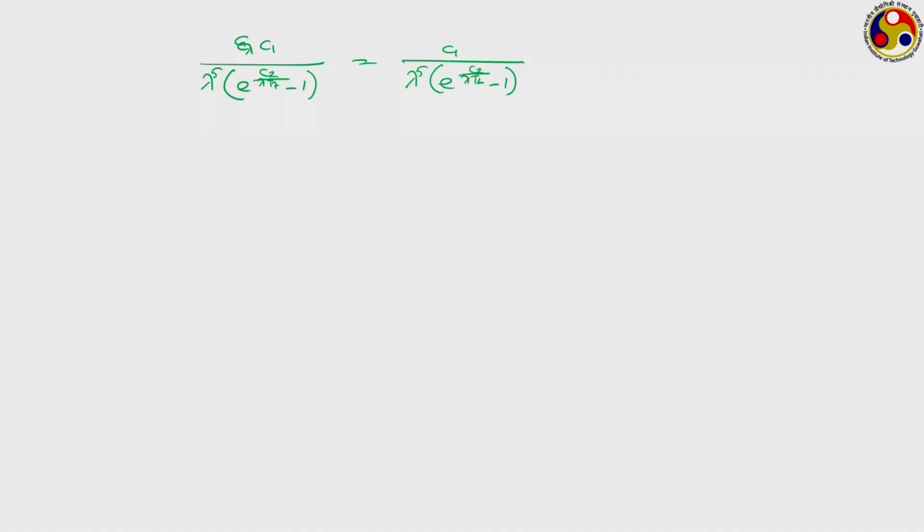Now, when the temperature is lower, as long as the temperature is lower than 4000 degrees Celsius, this exponent is too large compared to 1, so that the 1 can be ignored. So, we have epsilon lambda divided by exponential of C2 by lambda into the target temperature is equal to 1 divided by exponential of C2 divided by lambda TL.